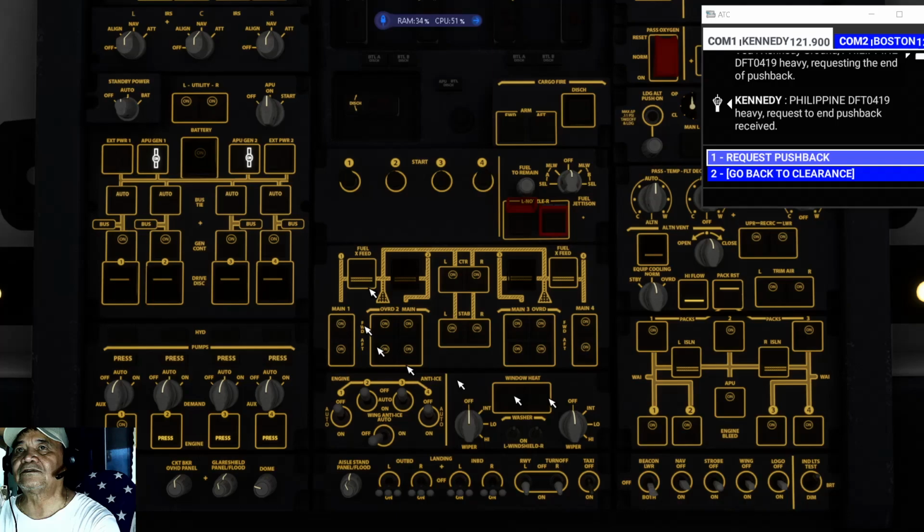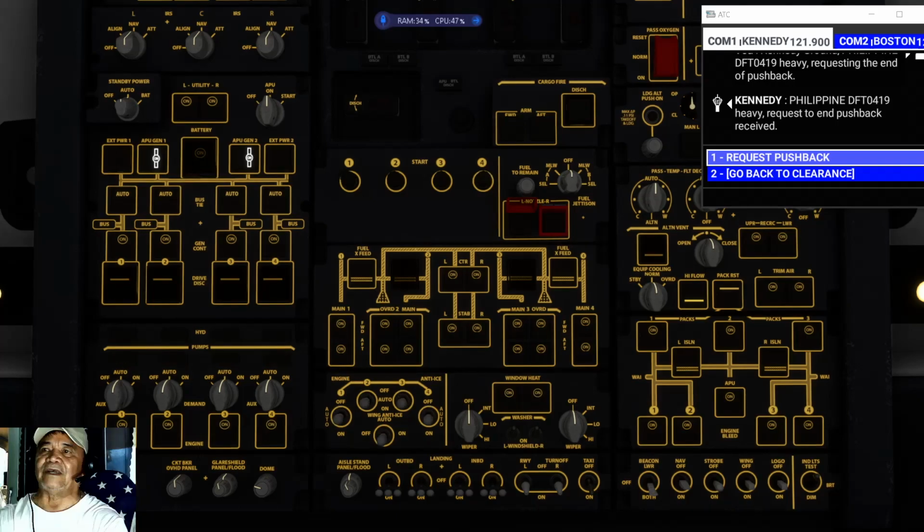It's on, and then automatic de-icing. Put it in automatic, because automatic is nice. If it is required to provide de-icing, then it will be provided by the automated system. If it doesn't require, then it's just standby. That is the advantage of this modern aircraft.